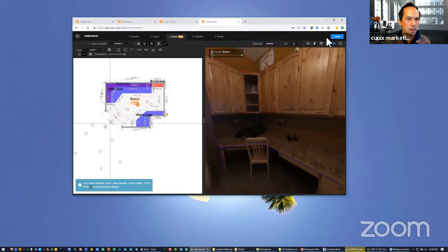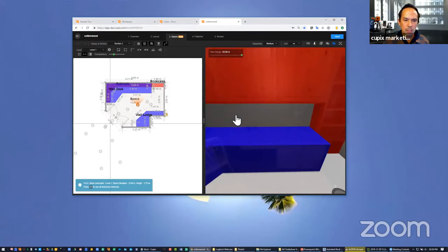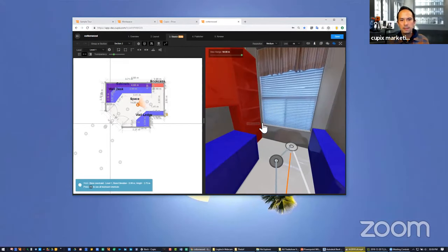So we can model this up into this kind of geometry, so you can use that where you need to. If you wanted to change the height of these things, you certainly could. But if you're thinking about modeling all those details, you'd be better off importing a CAD file into the Revit model and laying it right on top of where that geometry is.